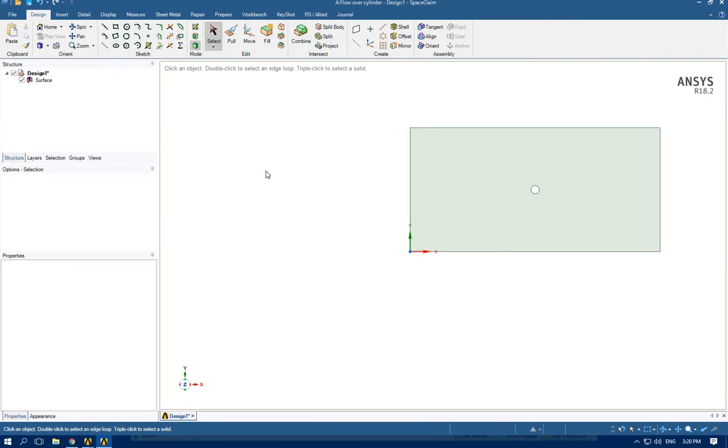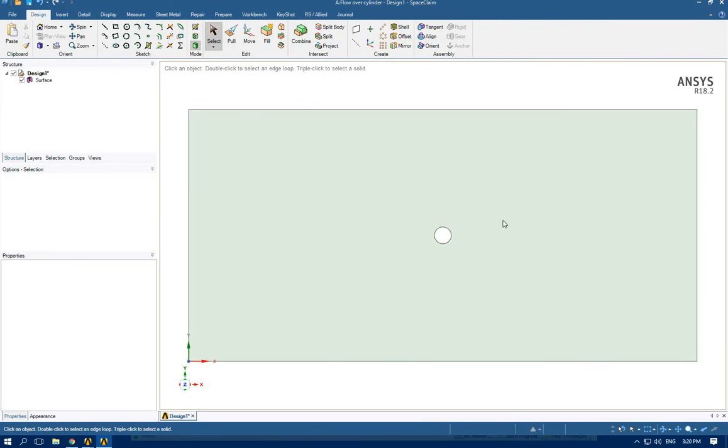Click the Z button to fit in all your drawing here. So this is my fluid region domain, and this hole is going to work as a cylindrical object. So basically we cut this building out of the fluid domain, and we are watching from the top.